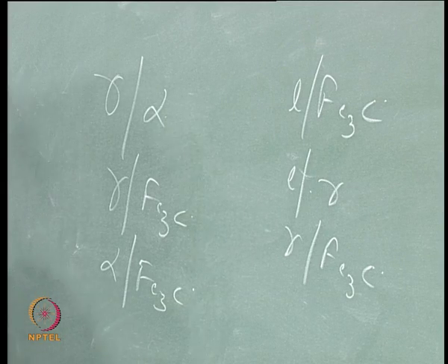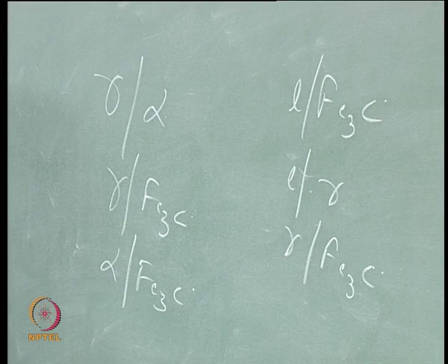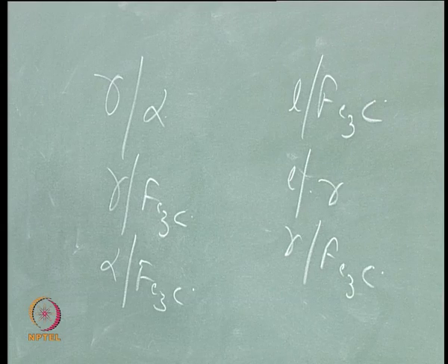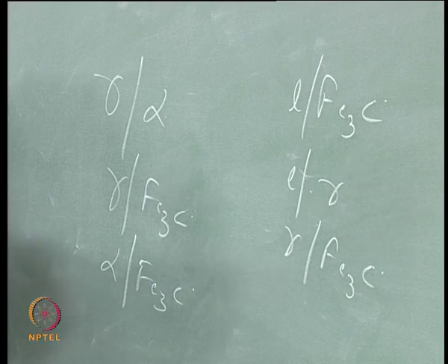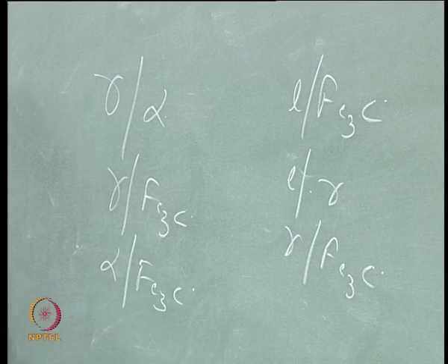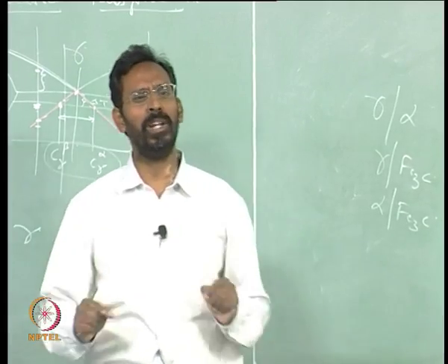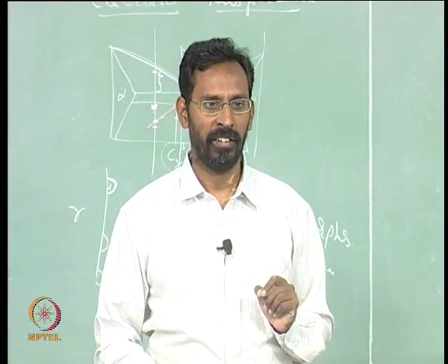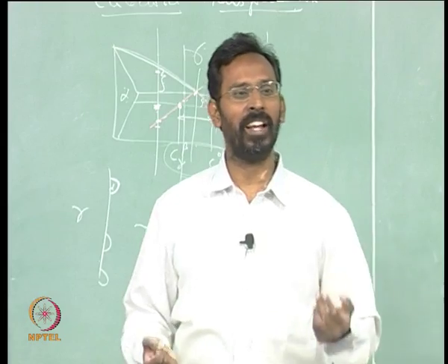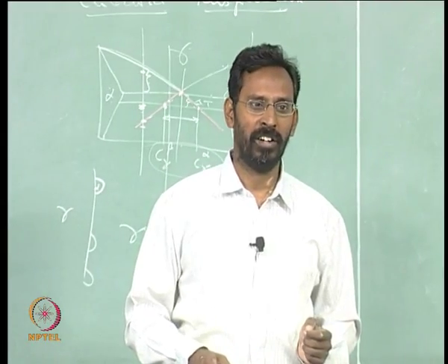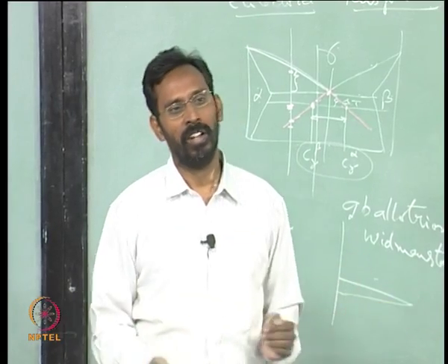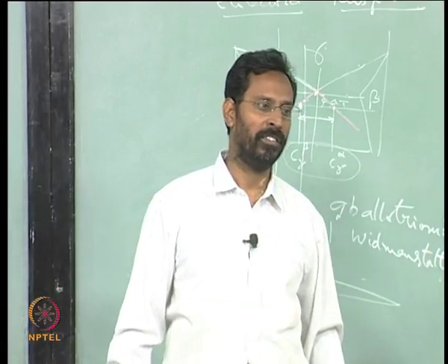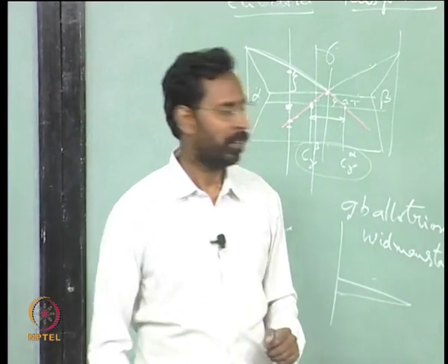Okay. When do you say interfacial energy is lower? Interfacial energy is lower when the structures are similar. For example, Ni3Al nucleating in a gamma phase, we say it forms very easily because the structures are similar. If the structures are not similar, the interfacial energies cannot be low. In fact, if you see a eutectic where both the phases that are coming out are cubic, you would invariably end up with lamellar eutectics, because the interfacial energies will be similar. For example, a copper silver eutectic will definitely be lamellar, if you go back and see, because both are FCC and there are no intermetallics in that phase diagram at all. It is a simple eutectic phase diagram. Okay.